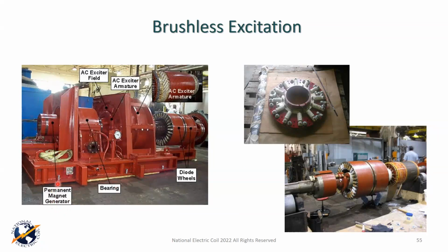The one thing from a safety standpoint I want to warn you about, especially on this design, is that those permanent magnets are extremely powerful. If your people go in there and play around and think they can remove one, the worst thing that can happen is it can injure the person. You can lose fingers and other things because they're so powerful. If you get them loose and they break loose, the force is just tremendous, okay?